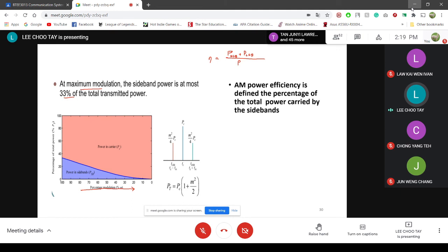Okay, so I can do a good filtering here at 10 times. But if I were to use a higher carrier frequency, let's say I straight away modulate to 500K for my AM signal, then I only achieve the same attenuation at 5 megahertz. 10 times 500K gives me 5,000K.